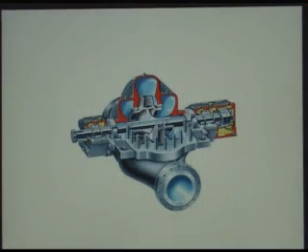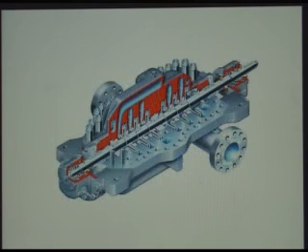So a couple of different styles of centrifugal pumps. This is what's known as a double suction pump, where you have flow coming in, and the flow is actually split, and it goes into a back-to-back impeller on the common shaft, and then comes out a common discharge. This is for extremely high flow rates. If you want extremely high pressures, you end up with a multi-stage pump, which operates in a similar method to the multi-stage compressor. Each wheel imparts